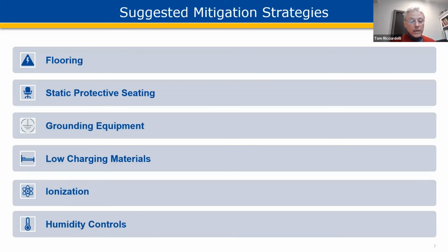Another one that's much more common, obviously, is humidity controls. In a healthcare facility, obviously, the environment is controlled for heating, cooling, and can be humidity. There have been some studies showing that controlling humidity can actually limit the spread of infections. There are certain microbes that don't do well in certain humidity environments. And that humidity generally is between, say, 40% and 60%, or some down to 30% to 60%. That humidity range actually is a very useful range for also controlling static. So if a healthcare facility were to implement humidity controls to help limit the spread of infection, those same controls in the same range would help limit the generation of static. And it can be a very effective tool. As many of us know, we experience shocks in the winter, but not in the summer, and that's because of humidity.